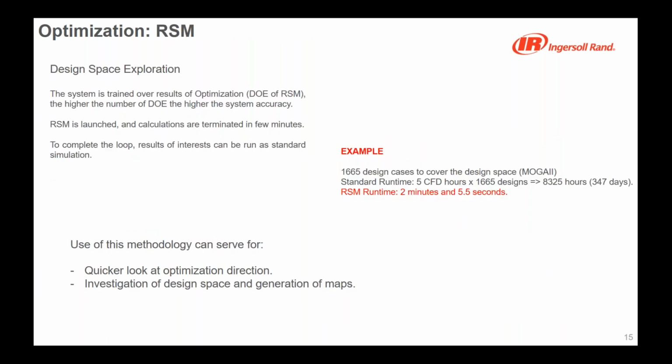But where I would like to spend a little bit more words is about the response surface method. And I'm going to look into that for the two stages case that I was also showing, where I have the two stages with the CFX flow that we have considered with no multi-point and no transient. I was just considering the design point CFX analysis.